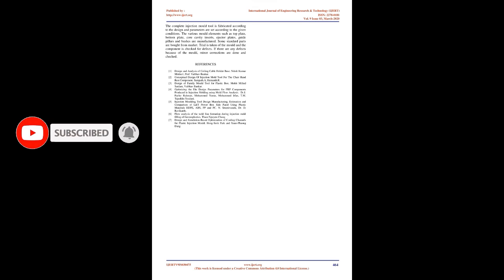Full mold design. The full tool assembly is designed. Elements such as locating ring, sprue bush, guide pillar, guide bushes, and sprue puller are designed according to the standard shape and size available. The guiding elements are for easy movement as well as accurate guiding. The Z-type sprue pullers are used to hold the shot in core half of the mold during opening. Rest buttons are given in between ejector back plate and bottom plate to give clearance between them so any dust or other particles do not cause any obstruction.